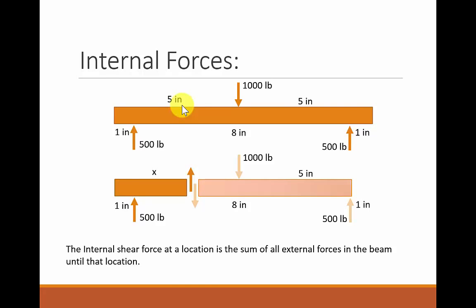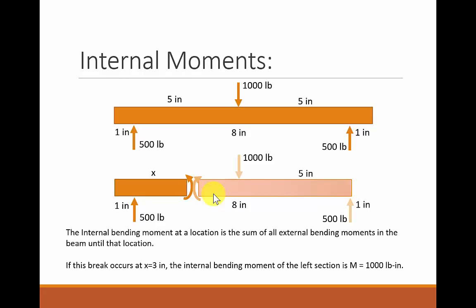And what we're going to say is that there exists some shear force at that location. And so we're going to sum forces, asking how this has to be reacting so that it is static at that location. And we're going to see that there are definitely some forces occurring there, and there are some moments occurring there. So we're going to calculate what those are, and we're going to use that to figure out what the stress is at that location.